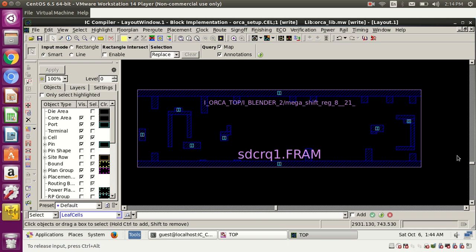Even for ports also we can get which ports are floating. Normally, to remove a port, we give the name with the remove port command. But if you want to remove only the floating ones, first you need to get those floating ports, then give that name.